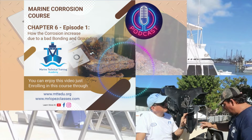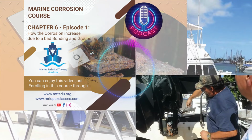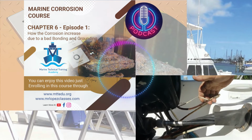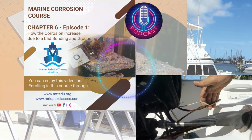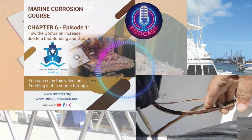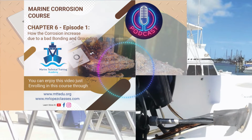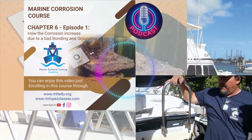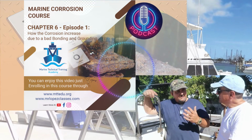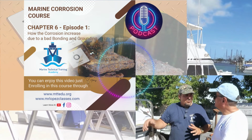But all of them will be corroded if the boat is not properly bonded, is not properly grounded, or if the boat is wet internally. If you have leaks of water, and those leaks of water accumulate on the surface, producing stagnant water, this is not good. And of course, the leaks of current. And we are going to learn in this chapter the process to identify where those leaks of current are.